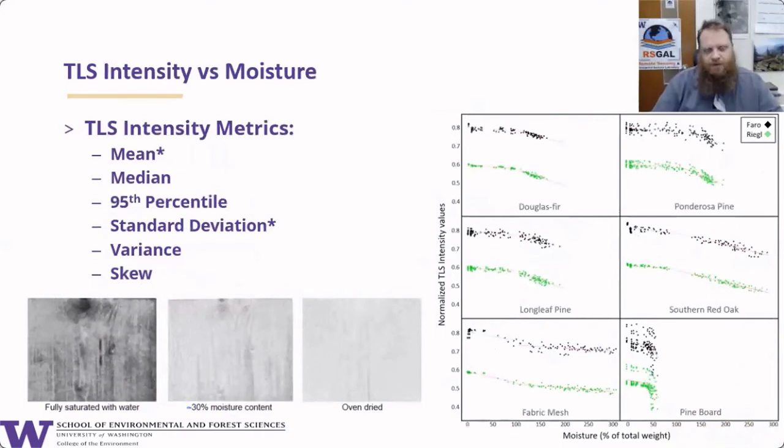From our scanners, the number of pulses per sample varied greatly, of course, depending on the distance from scanner. The Regal scanner had upwards of 100,000 pulses per sample tray at 3 meters, where the sample trays were about 30 centimeters square. The Faro had fewer returns per sample tray, but still upwards of about 30,000 at 3 meters, decreasing to about 900 for the Faro at 12 meters.